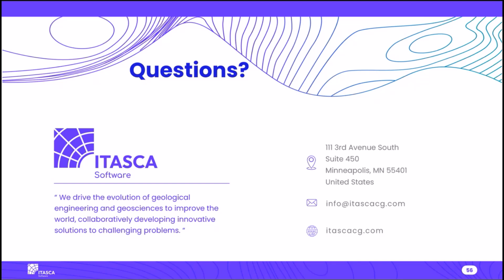For Rayleigh damping, we usually cover the target damping at this natural frequency and some factor of that natural frequency, for example, 5 times or 3 times. And for Maxwell damping, usually we need to calibrate the almost constant damping between those two frequencies, or a little bit extended range to cover that frequency. That's my practice.